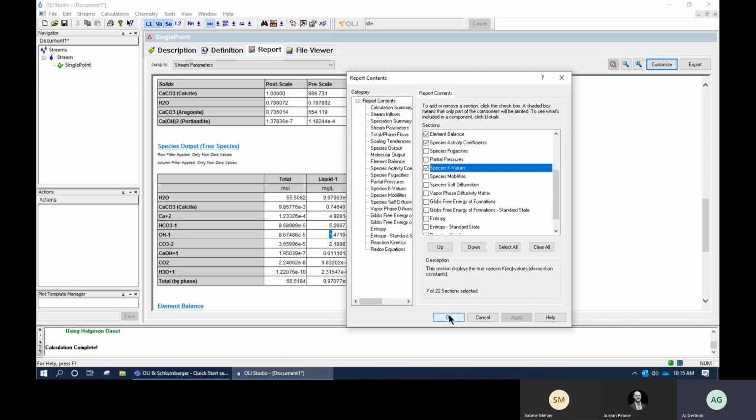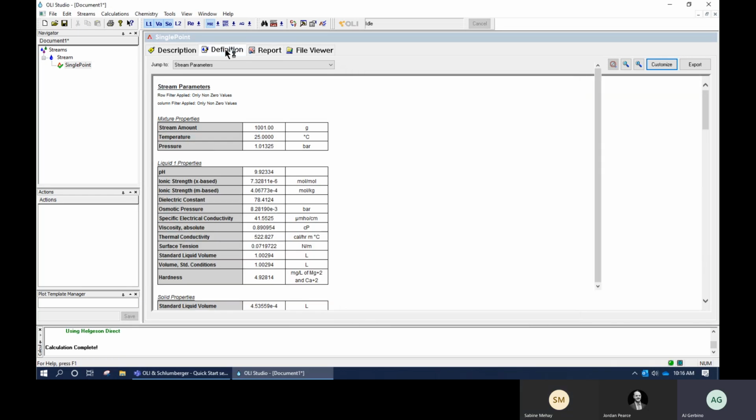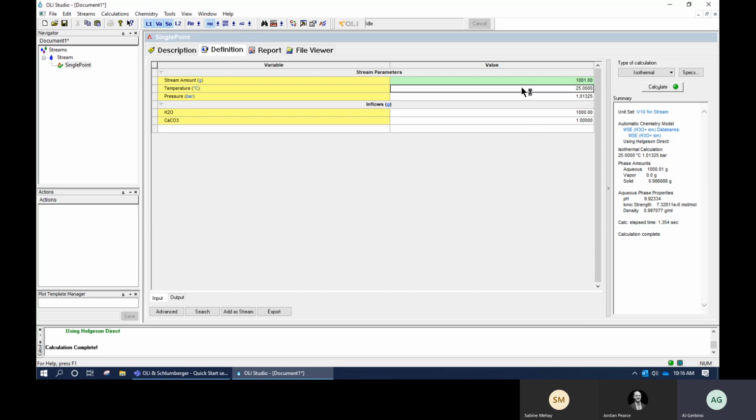There's nothing in the gas phase. It's because we're looking at flash data. That's right. So I'm going to explain that. I want to bring that up now. I was saying before, ambient temperatures and pressures. When we look at pressure here, what we're essentially talking about is a hypothetical plunger on the top of this material. So if the bubble point of this doesn't, if the vapor pressure of this does not exceed the confining pressure, there is no vapor phase.